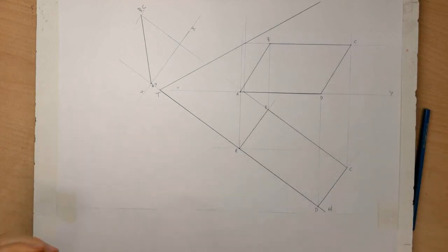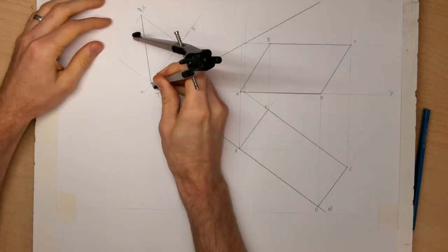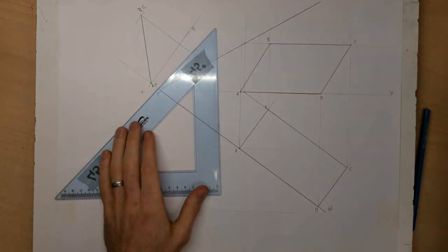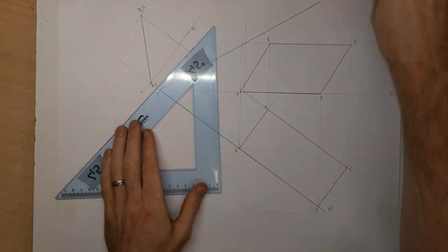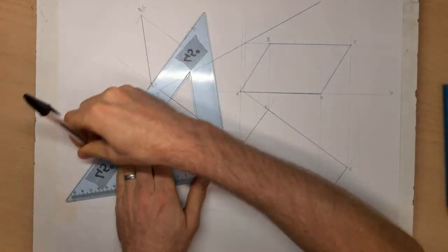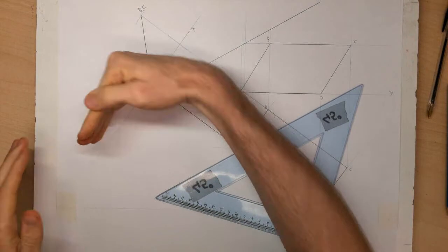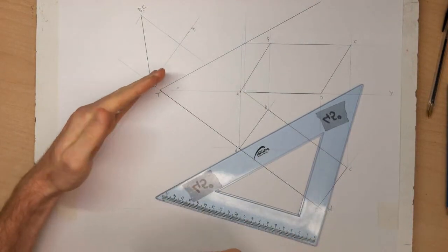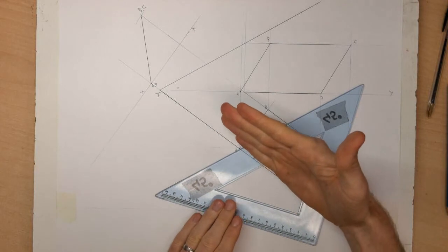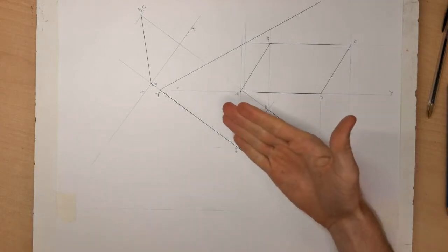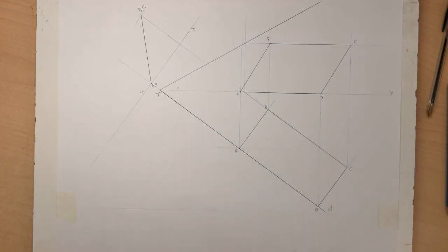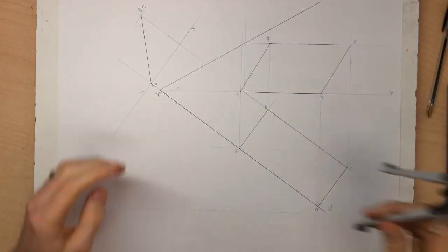So let's rotate AD. So just extend on my horizon line, or horizontal plane. So I'm going to rotate this down so it's resting on the horizontal plane, projected down, so that it's essentially rotated from this position, so rotated from that angle position down, sitting flat on the horizontal plane.